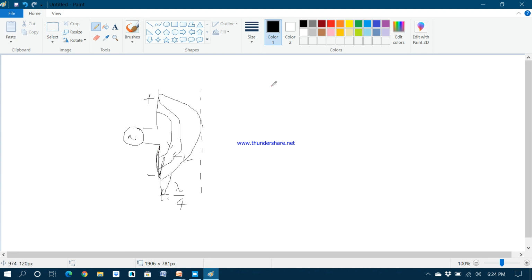After hitting the ends of the dipole, at the next time period, that is another lambda by 4 time period, these waves are reflected. If this wave has a polarity from positive to negative applied here, the same thing is reversed here.